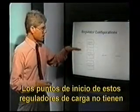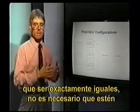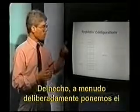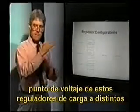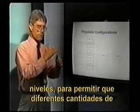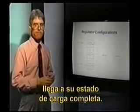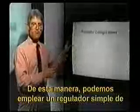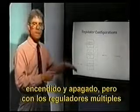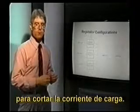The set points of these charge regulators do not have to be exactly the same. They don't have to be synchronized in any particular way. In fact, we often deliberately set the voltage point at these charge regulators at different levels to allow different amounts of current to be cut off as the battery reaches full state of charge. In this way, we can use a simple on-off type of regulator, but with multiple regulators, we effectively get multiple gentle stages of cutting down of our charging current.